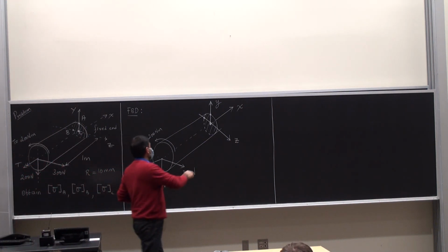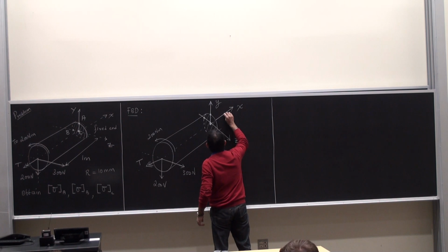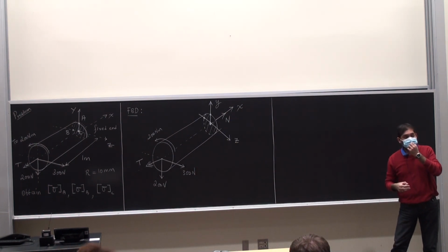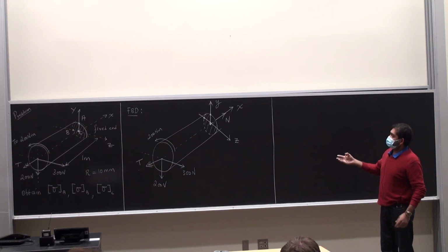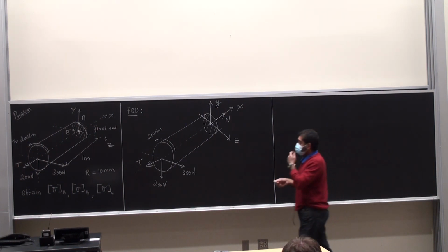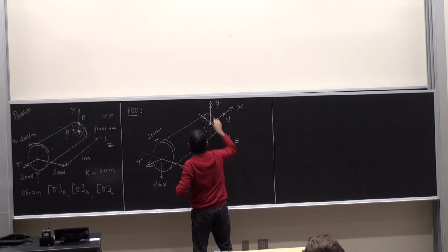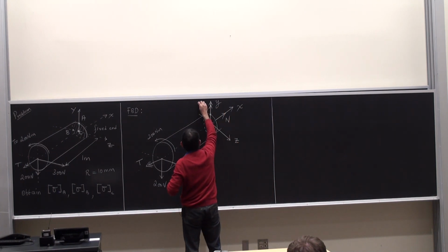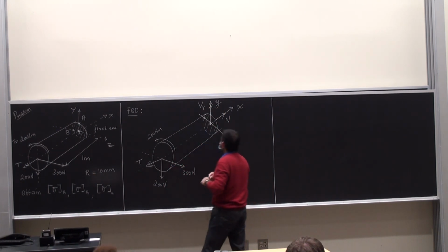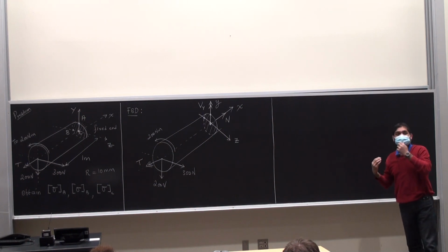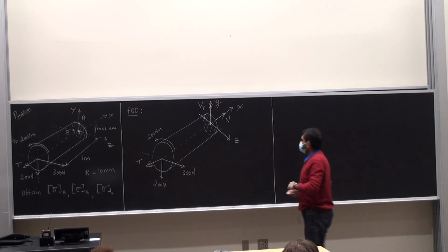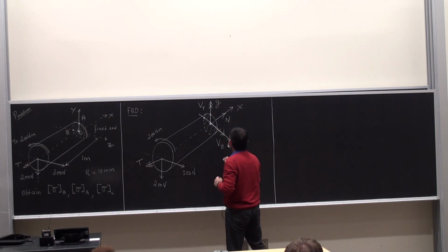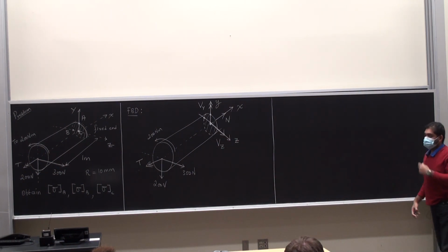Okay? So my first reaction force is going to be a normal force, coming out of the cross section at the end. Then my second reaction force is going to be along the y-axis. I'm going to call it V suffix y. Okay, those are my reaction forces, and I'm going to have one more along the z-axis. Makes complete sense to point it along the positive z. Call it V suffix z. Those are my reaction forces.